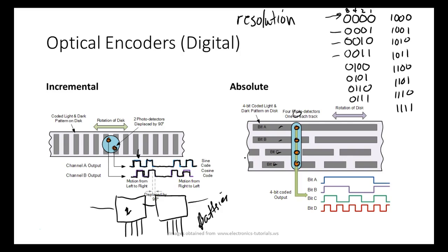Now you can still go out there, and we call it jogging the robot. You can manually move the robot, but you won't run any programs. Because when manually moving, you're looking at the robot, right? So the controller doesn't have to know where it's at. It's you that's controlling the position of the robot.